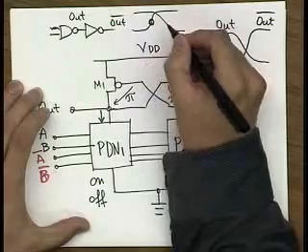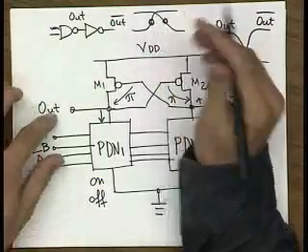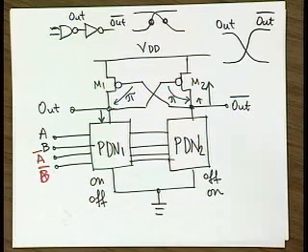So this is when your out becomes available and this is when your out bar becomes available. So you have a sort of timing mismatch between these values. This can be useful for certain functions, such as when you want to implement XORs. That is fairly useful and readily used in the implementations of adders, when you have a lot of XORs and both true and complementary signals. And then we will see that in a moment.